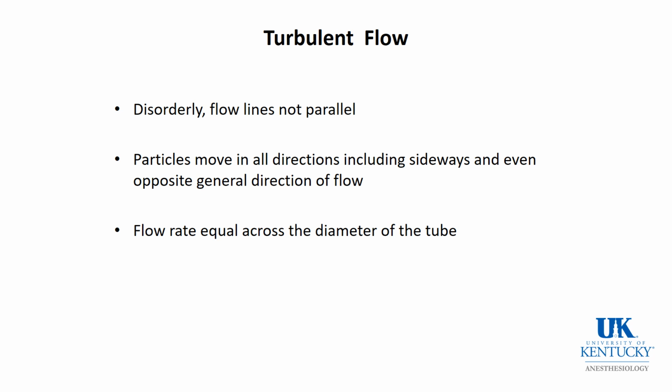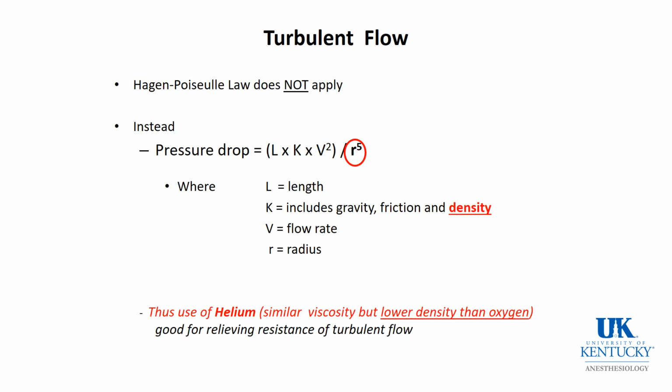Turbulent flow is disorderly. The flow lines are not parallel. The particles move in all directions. And Poiseuille's law does not apply to turbulent flow in two regards. First of all, it's influenced by radius to the fifth power. And secondly, instead of viscosity, it's influenced by density.